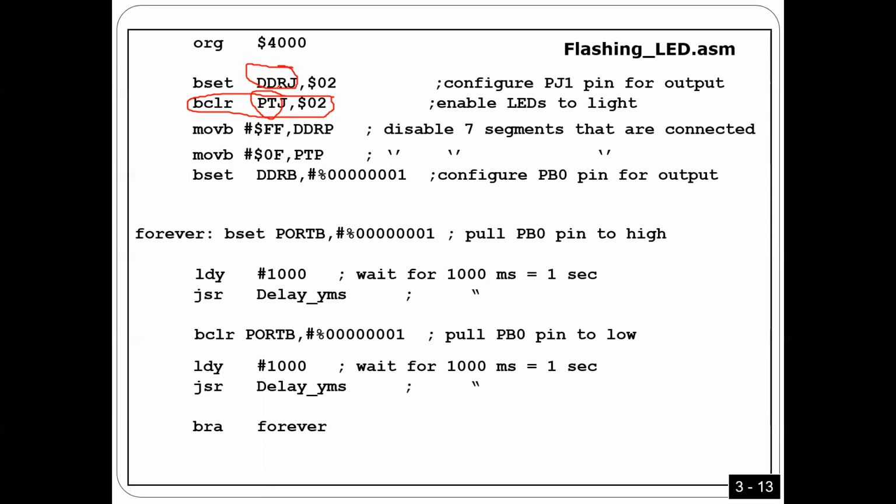Every port should have 2 registers. One for configuration and the other one for the data itself, if you want to read or you want to write, right? So this one is for direction, but this is the data itself. Okay. So here by doing that, I put 0 in this pin in PG1. So after this instruction, PG1 is 0. Is that okay, guys? Okay. Now I'm okay with PG1.